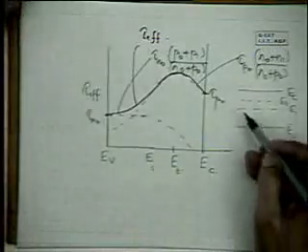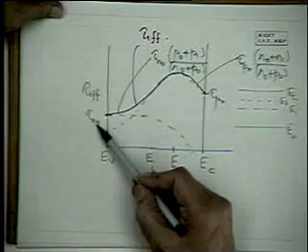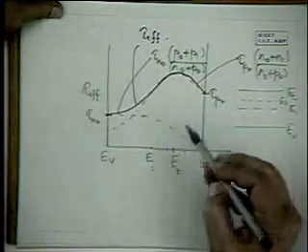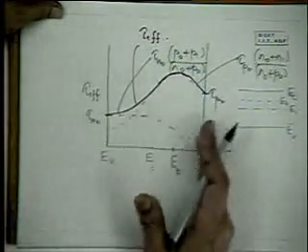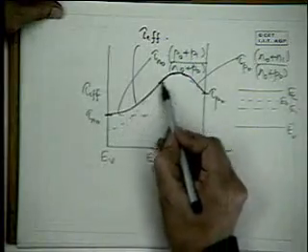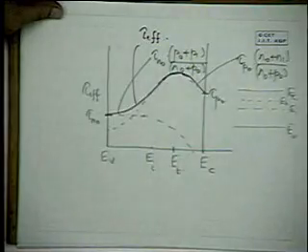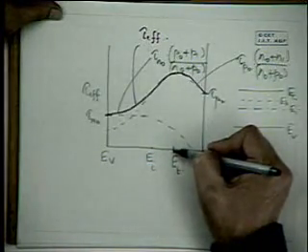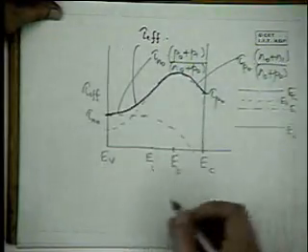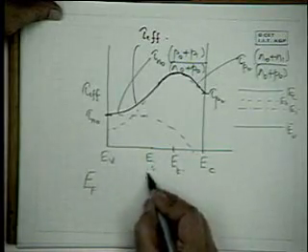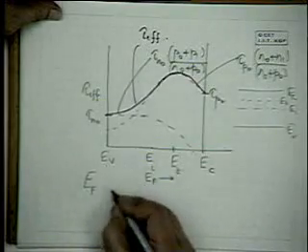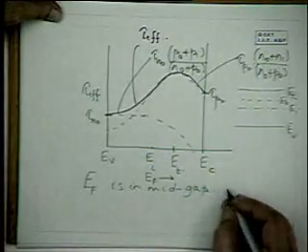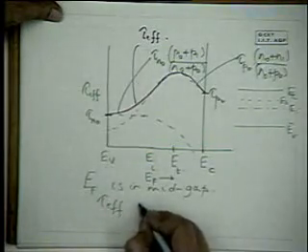This shows that when we talk about minority carrier lifetimes being tau N0 in p-type material and tau P0 in n-type material, these are the extreme cases. In general, the Fermi level is somewhere in the band gap. It is not here, it is not there. So in general, the effective lifetime follows this curve. Obviously you can see that as EF is varying from here to here, when EF is in the mid gap, tau effective goes through a maximum.